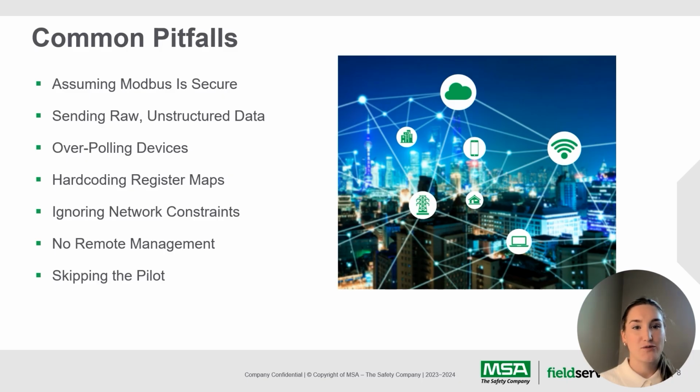The first would be assuming that Modbus is secure. This is probably the number one misconception, that Modbus is somehow secure because it's old or running on a closed network. In reality, Modbus has no built-in security, no encryption, no authentication, like we mentioned before. So if you're exposing Modbus traffic over IP, especially public networks, you're wide open to threats. That's why your gateway should provide TLS encryption, certificates, or access control from the edge. Security should be designed in, not just assumed.